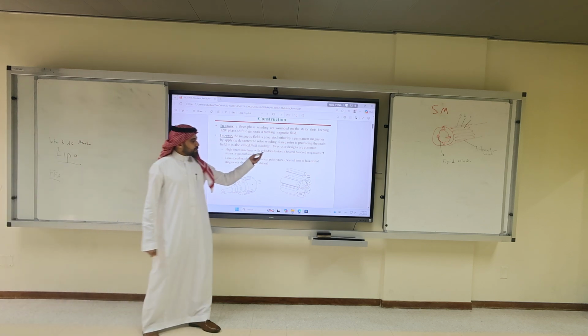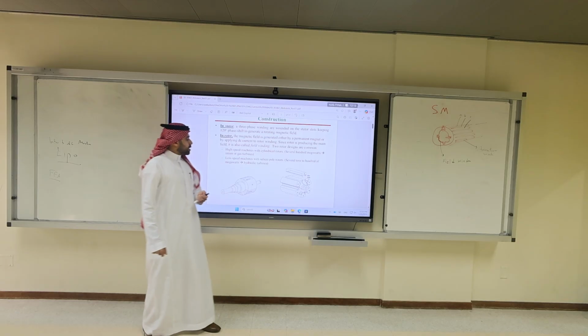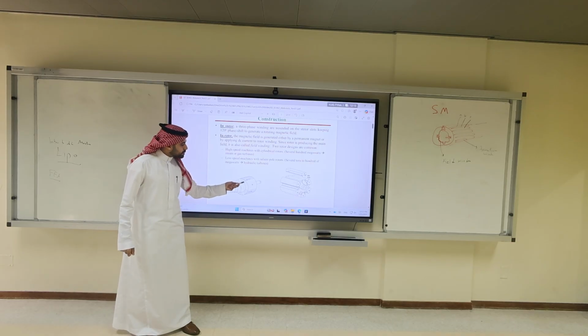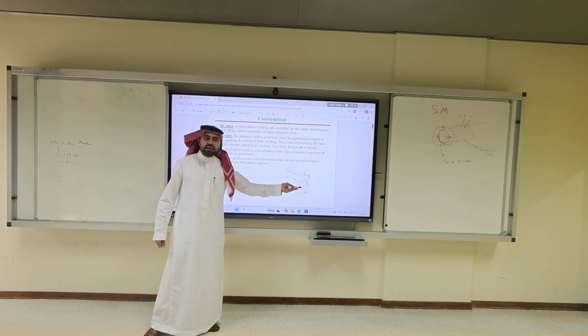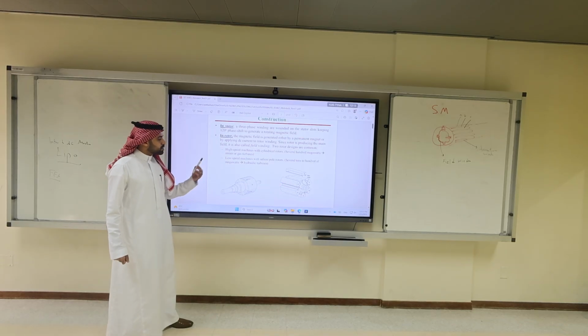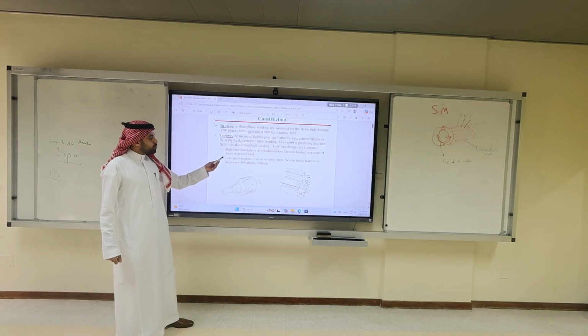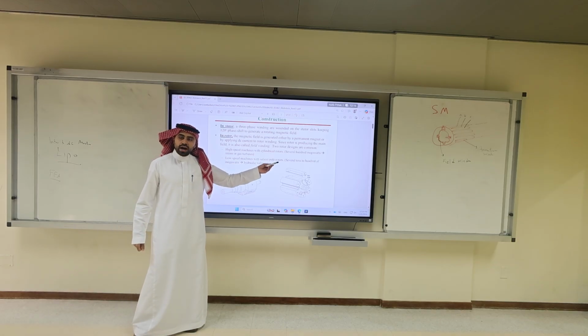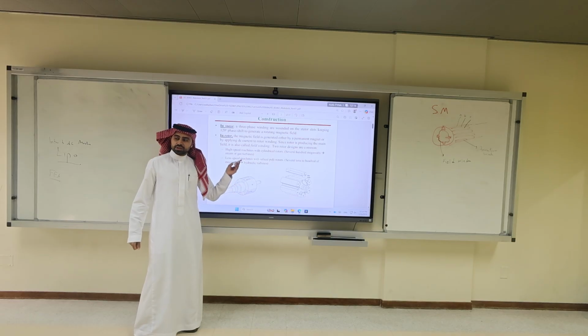For high-speed machines, usually the number of poles is not that much. We want to have round rotors. Why? Because the salient pole will cause air friction. But for the vast majority of synchronous machines, we have a high number of poles, and because of the high number of poles, the speed is slow.